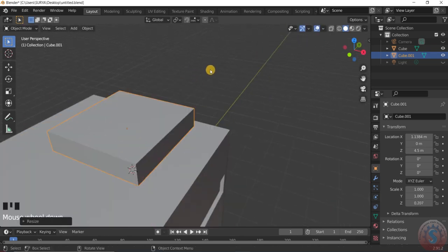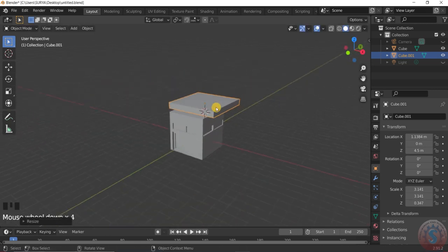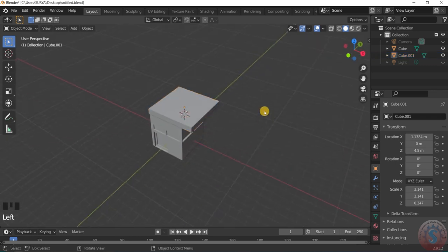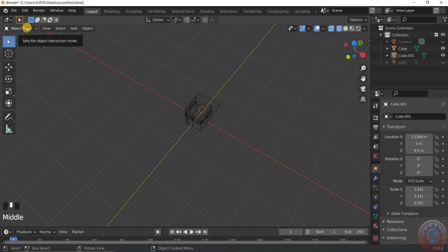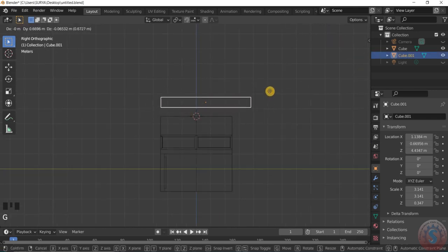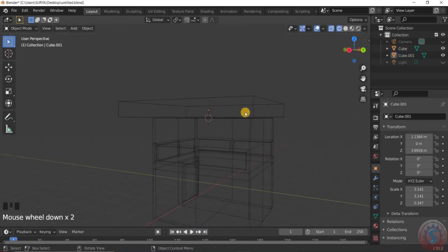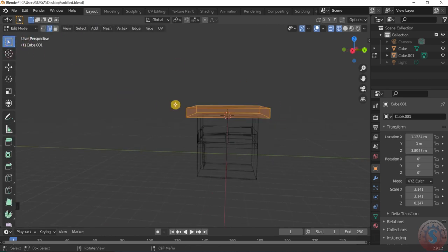I want to give some thickness value to this by pressing Z again, and I want to press S and enlarge this some distance, and then after Z go into the wireframe mode and onto the 3. You can observe I'm selecting this, go to G and the X, Z key, and give it exactly onto the edge top in the edit mode.